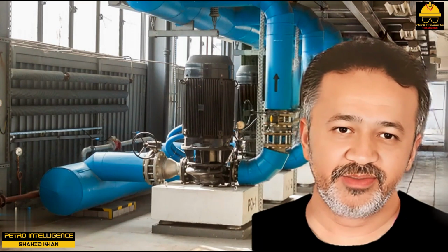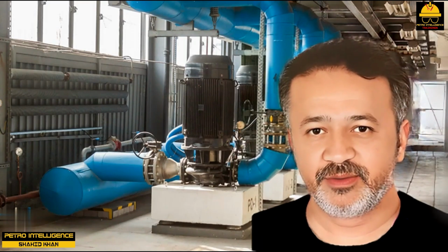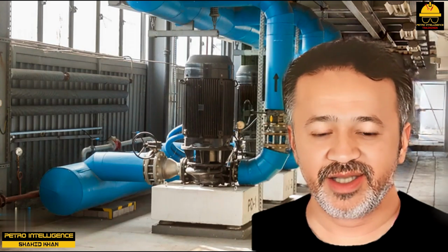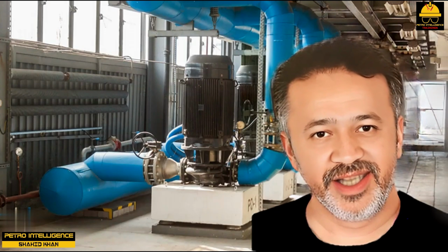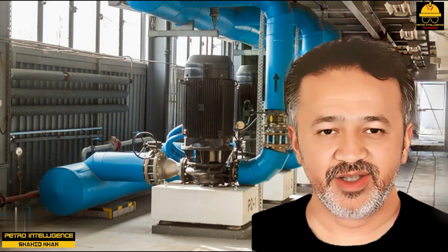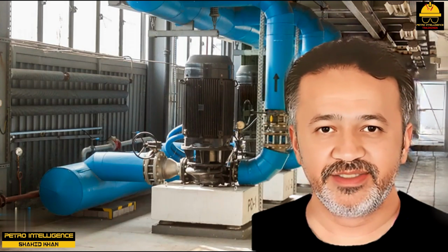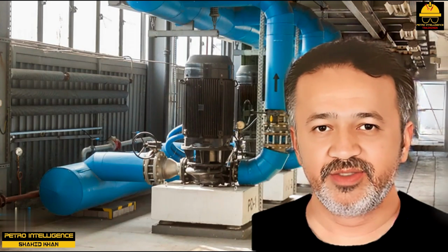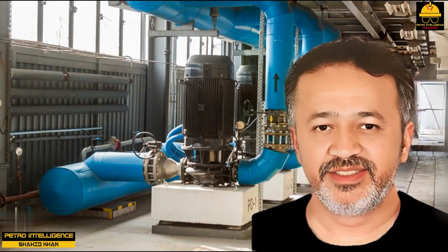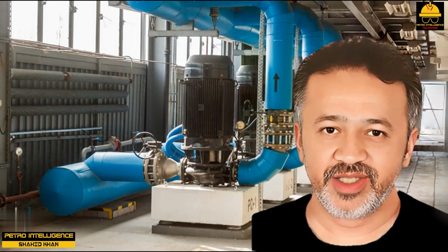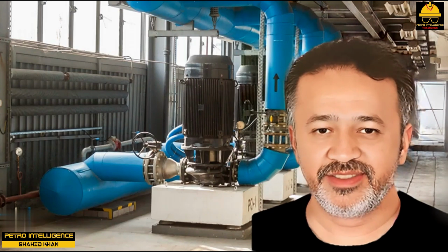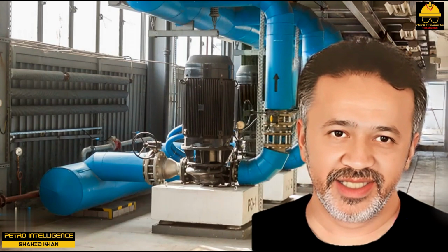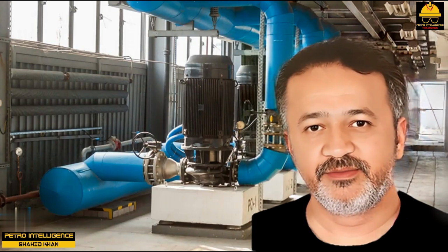If the flow of water is cut in half, then the momentum of the water flowing in the pipeline is also cut in half. This energy cannot simply disappear. It has to go somewhere. The energy is converted to an increase of feet of head in the sump, that is, the water level in the sump jumps up and blows the manhole covers off the top of the sump. Incidentally, this is a true story. Can you imagine what would have happened if all 6 pumps failed simultaneously due to an electric power failure? The result would be a dramatic lesson in the meaning of water hammer.